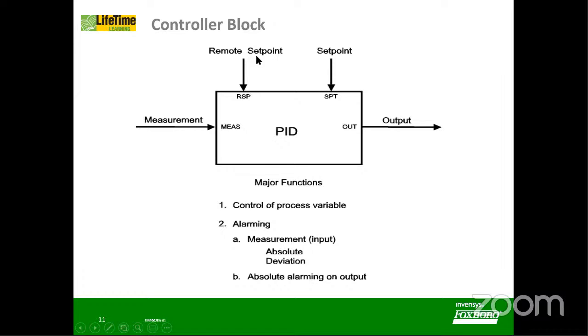At any point of time, let us say you have one simple closed loop system where you are taking the input, giving it to PID and taking the output. But depending on the functionality or requirement, you want to change the closed loop control system into cascade control. In that case, it is simply one button click by the operator.